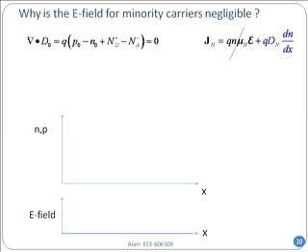So what's happening? You remember that in equilibrium, if it is a homogeneously doped sample, as was the case for the example I just told you about, in that case, the electric field will be zero, because N naught and P naught and Nd plus and Na minus, they will conspire together to make the electric field locally at every point equal to zero. So that was not a problem. Now, remember that this was an acceptor doped region, right? That's how we set up the problem. In an acceptor doped region, I can say that P naught is equal to Na, right? In equilibrium, I can say that.